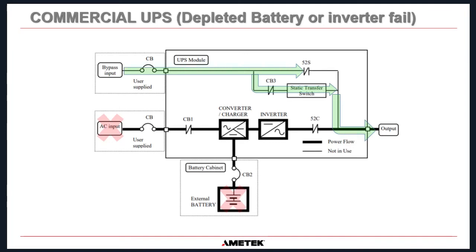And in a commercial UPS, the static transfer switch in most cases is not rated to carry the load all of the time. It's just an instantaneous transfer.